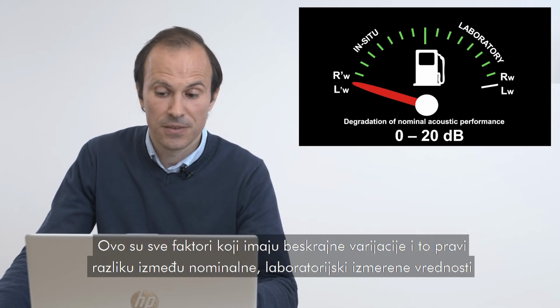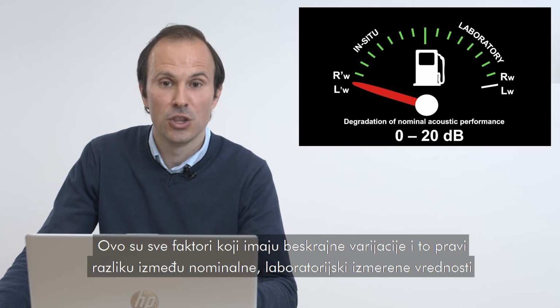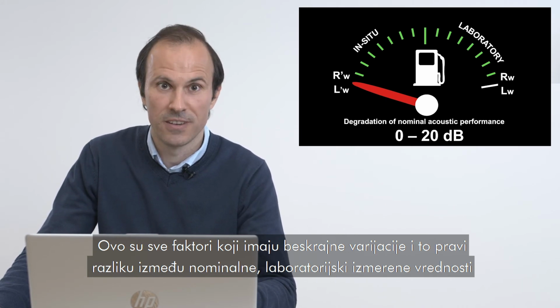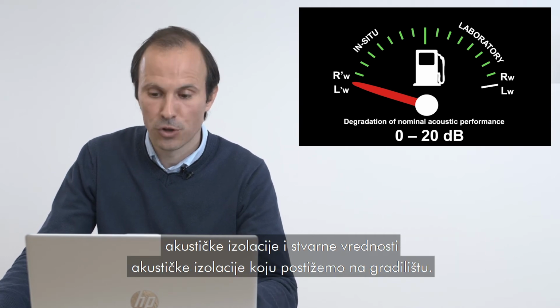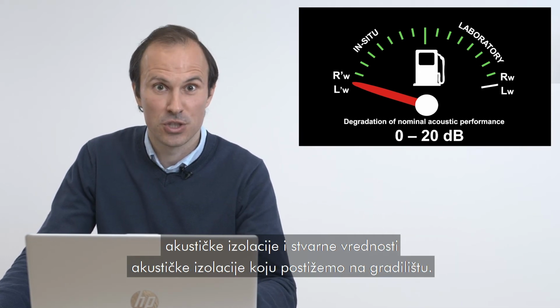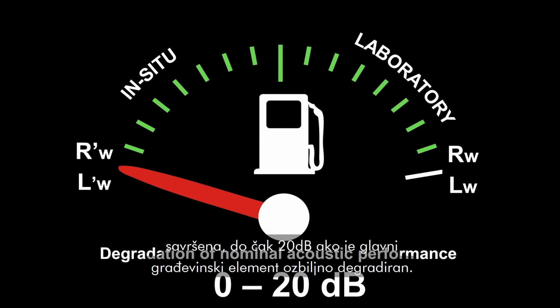All of these are factors which can have endless variations that can cause a difference between the nominal, laboratory measured value of acoustic performance, and the actual value of acoustic performance which has been achieved on the construction site. And the magnitude of this degradation can vary from 0 decibels, if we manage to make our installation close to perfect, to even 20 decibels if our principal building element is severely degraded.